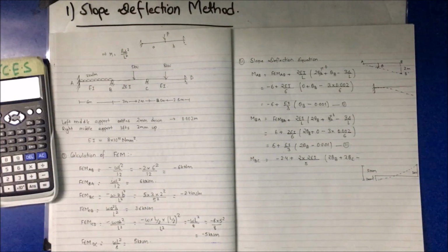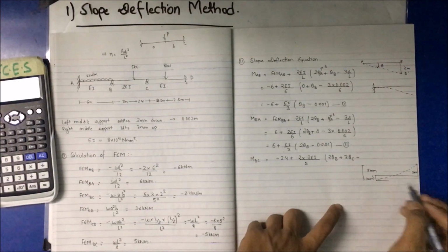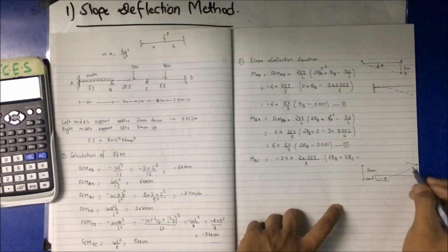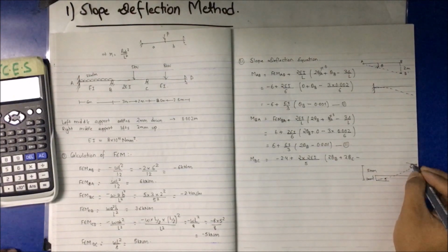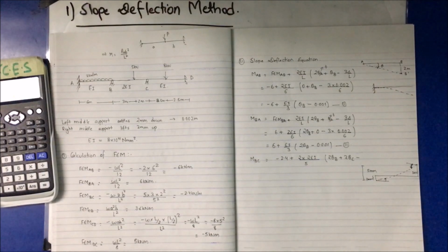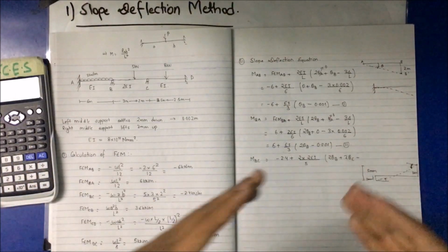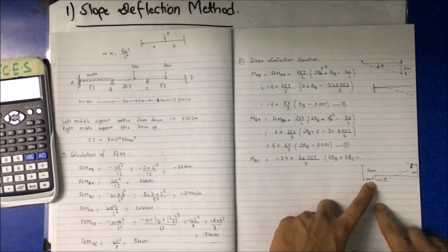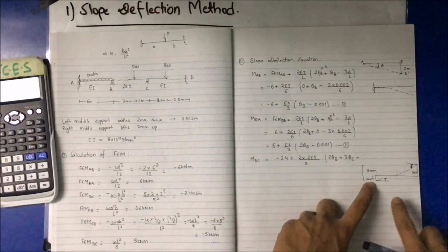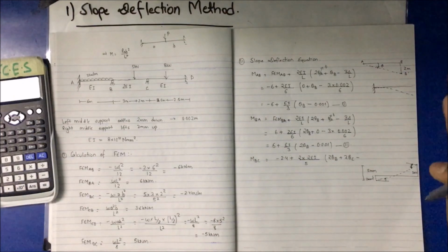The overall displacement is 5 mm, and the sign, if you see, is anti-clockwise by making with the tangent. So for anti-clockwise we take displacement as negative. If both were in the same direction, the displacement would have been different. For example, if this has displaced by 3 mm downward and this also displaced downward by 5 mm, then the overall displacement would be 2 mm only. But in this case both are in the opposite direction, the net displacement will be 5 mm here.